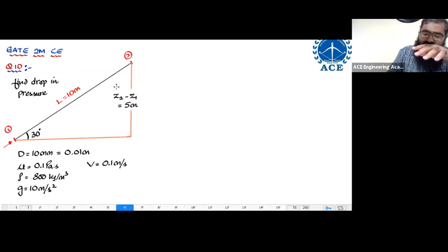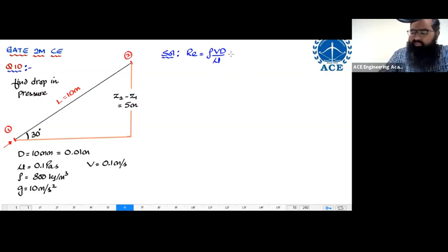So whenever these kind of questions are given to you, always start the solution with finding out the Reynolds number. It will be helpful. The Reynolds number, Re, we know is equal to rho VD by mu. You don't need a calculator for these very simple numbers.